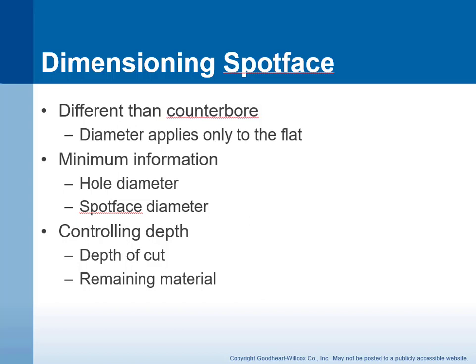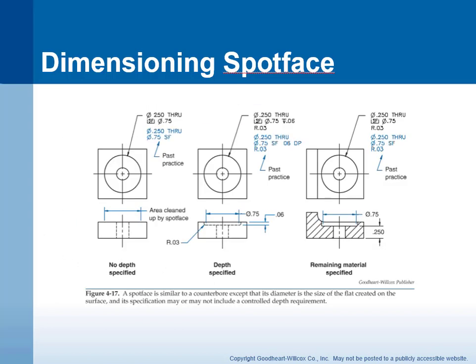To control the depth of a spot face, kind of like a counterbore, you would dimension either the depth of the cut or the remaining material. Here are some examples of spot faces. Now, a spot face is just a little bit different. When I think of a spot face, I like this feature right here.